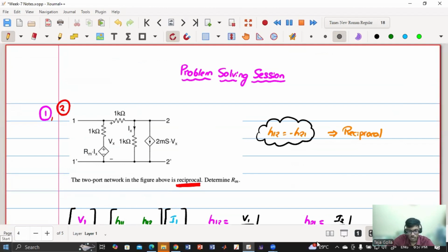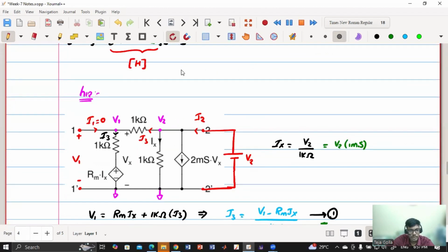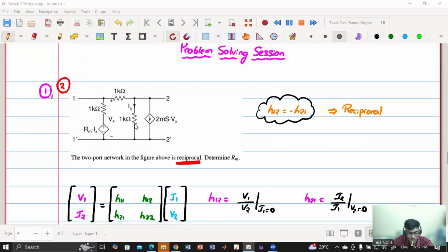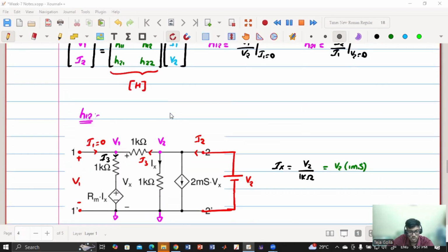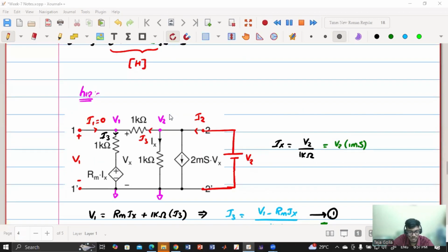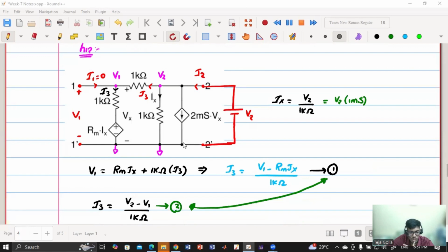Sir, in the previous circuit, how have we selected the ground terminals? So in any circuit, if the ground terminal is not given, I am free to select the ground terminal, and I will select it in a way that is comfortable. If this is the voltage source that is connected, and I consider the bottom terminal as ground, the top one will be V2.